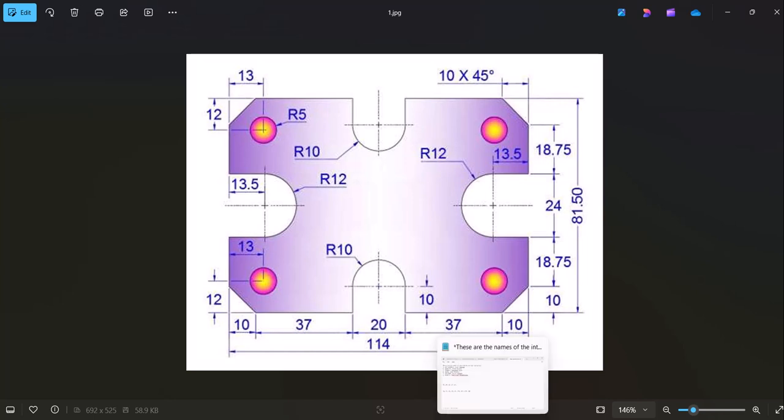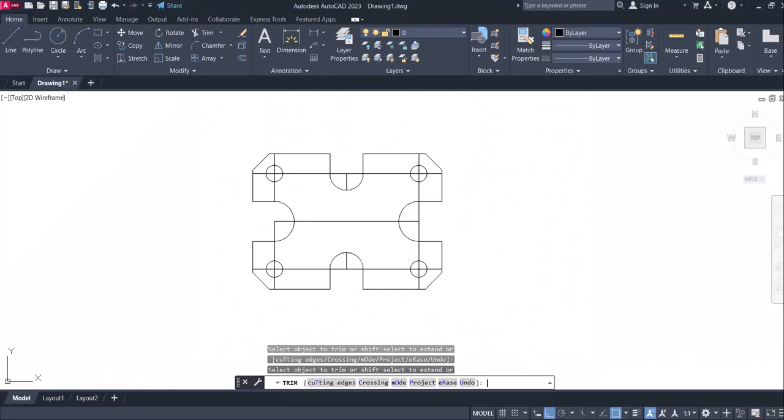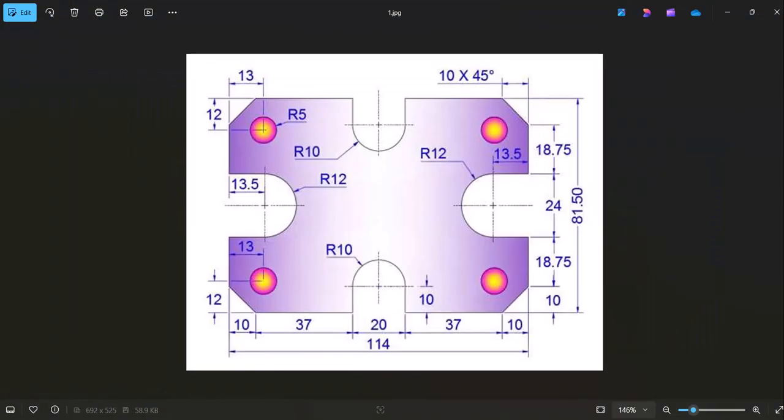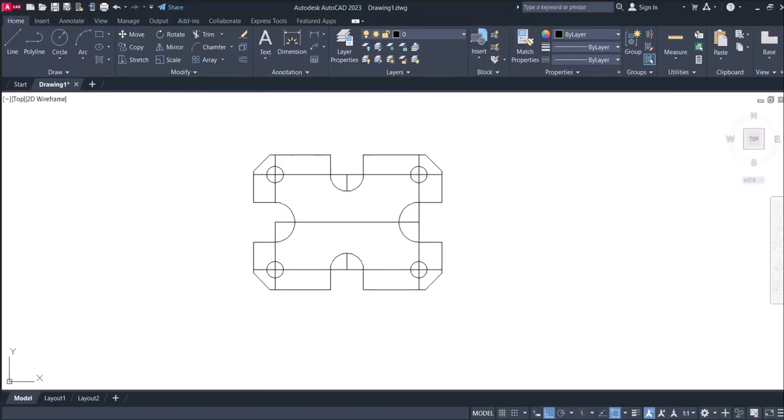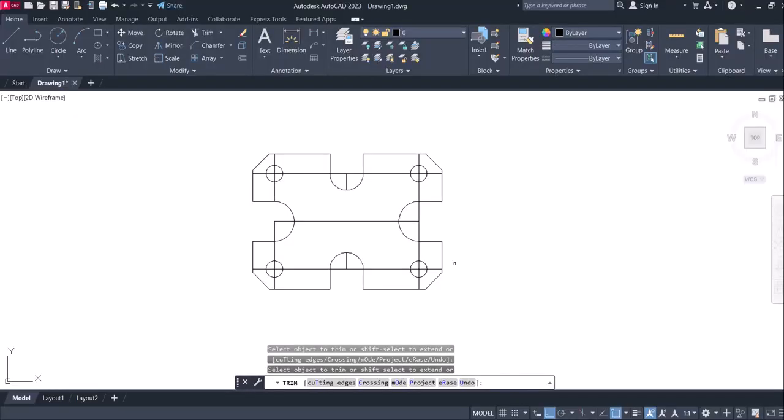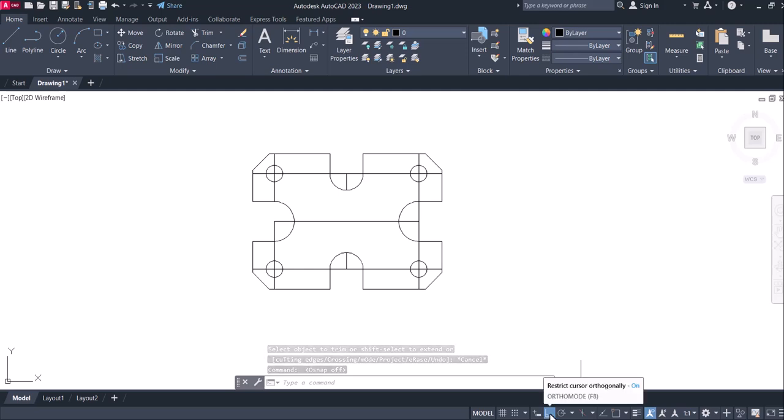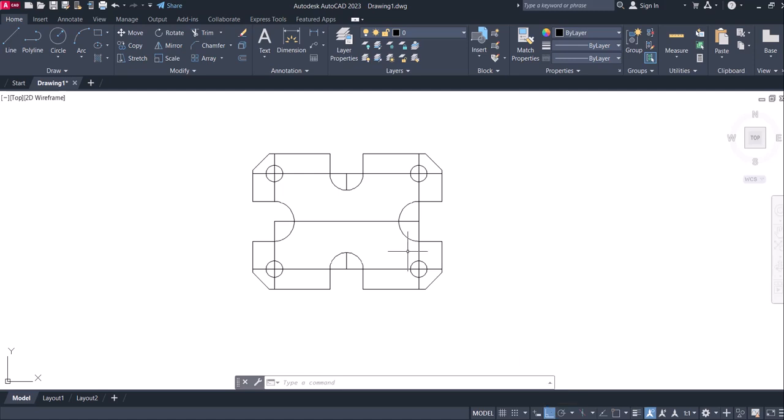So now the next thing I'm going to do is just to adjust my construction lines so then I can do the finishing. Let me press escape. Now my auto is still on. I'm going to put off my object snap but my auto is still on. Auto being on means that I will still be able to maintain my vertical and horizontal movements.